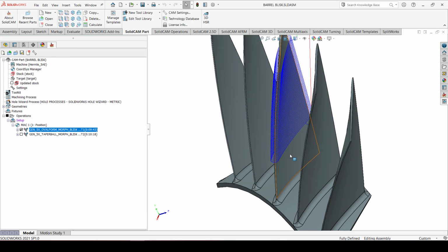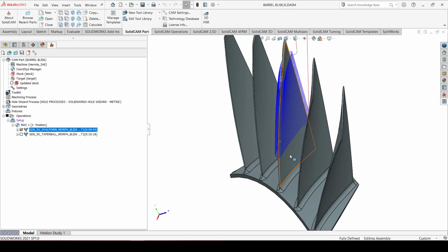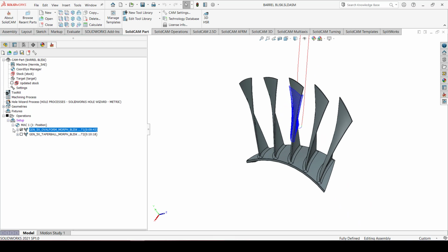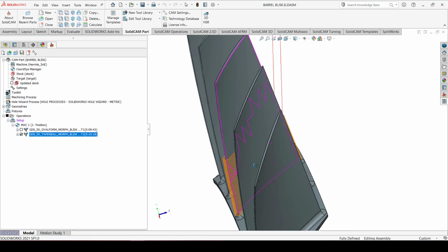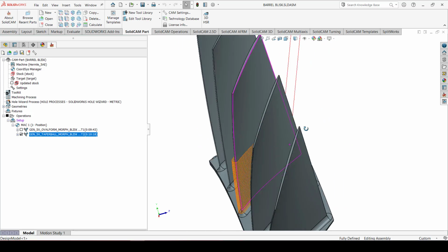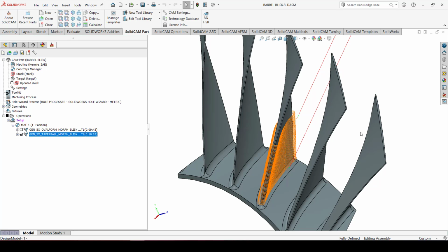Beyond this, it's difficult for the tool to go because of the limitation of the length. Whatever remains can then be machined again using generic, but using a different tool. So you can see that the generic machining is capable of handling not only regular standard tools but also the new generation tools like barrel tools, oval form tools, or lens form tools.